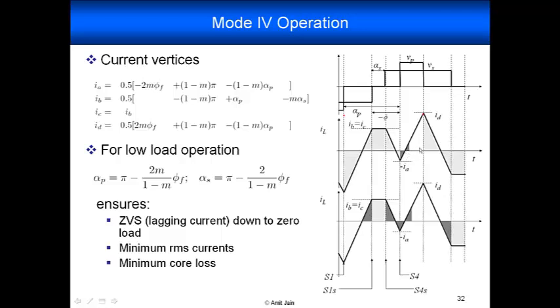So we're getting two zero crossings going from negative to positive, and this is required to obtain zero voltage switching for all the switches. So because M is less than 1, we are looking at zero voltage switching for the secondary side bridge, which is what gets compromised first.